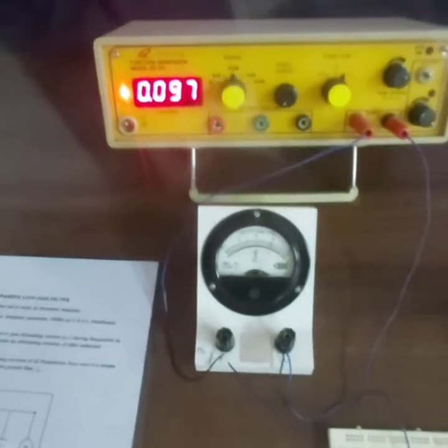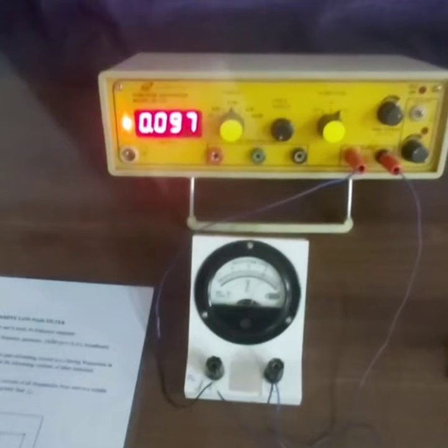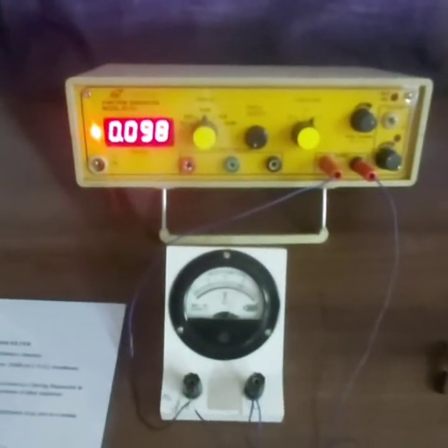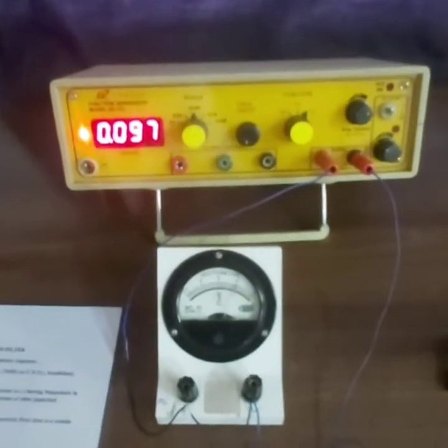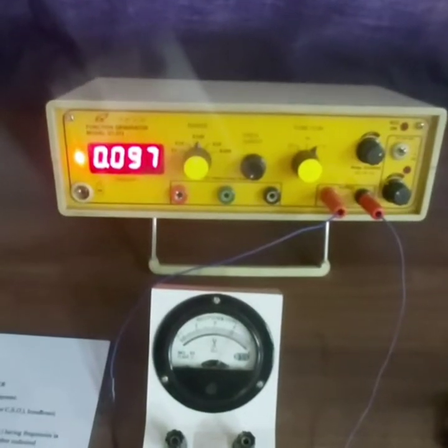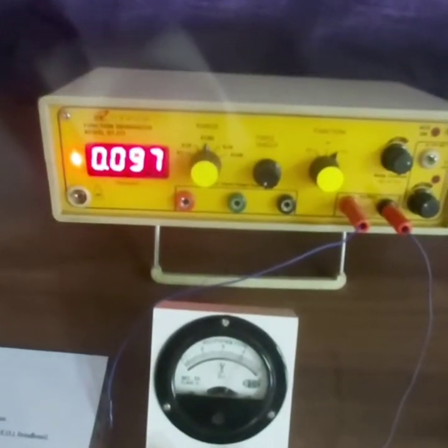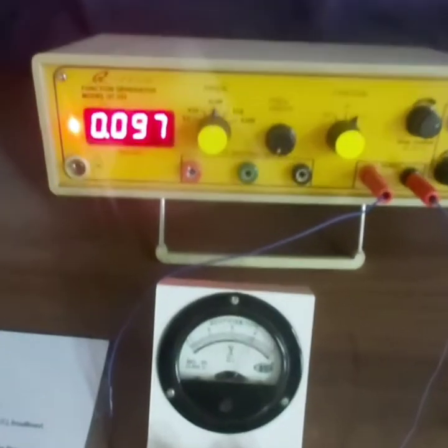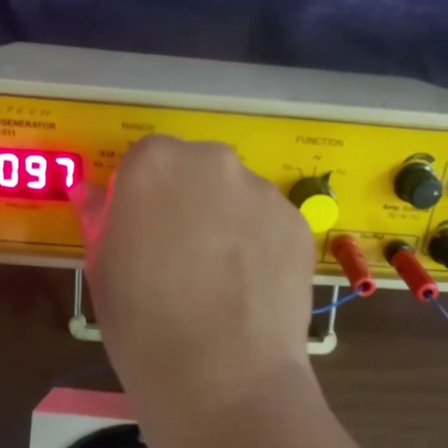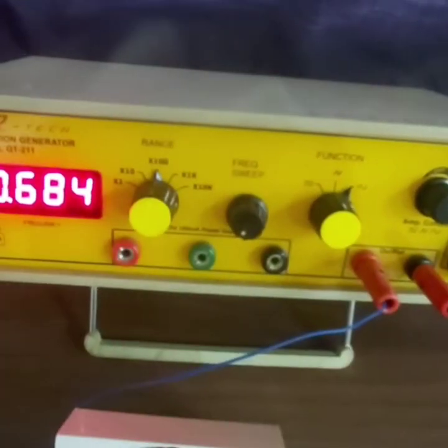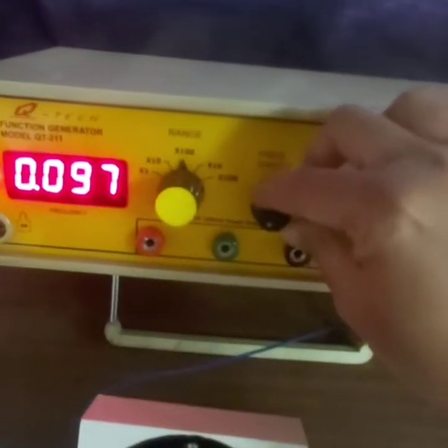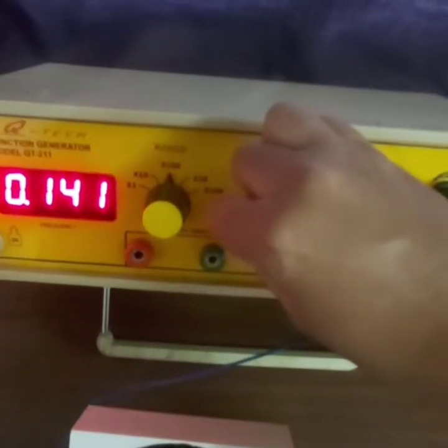Here you can see the display which shows us the frequency. So we can change the frequency. I hope you can now handle the signal generator because you have performed the LCR experiment where a signal generator was used. So here you can see the range. This knob is used to change the range of frequency, and within that range, smooth variation is given by using this knob.